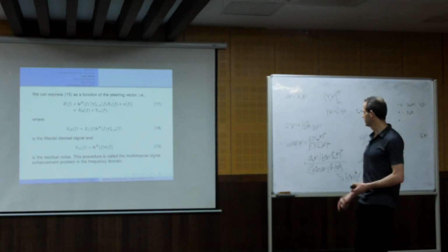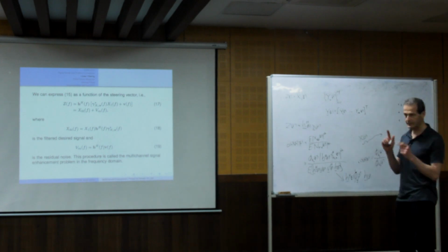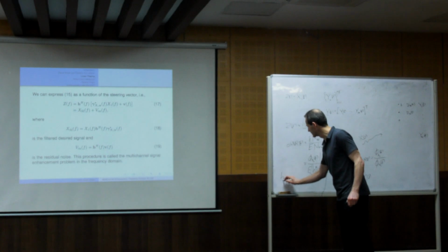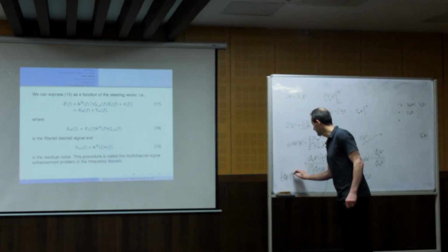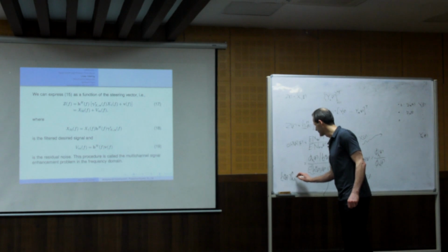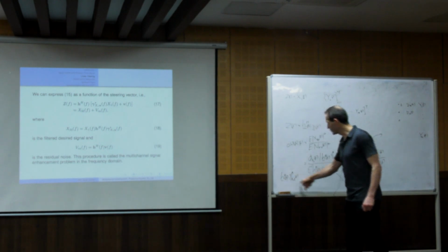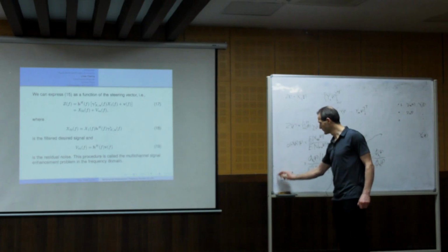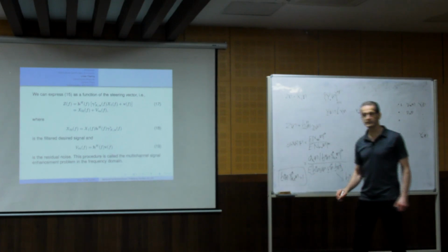Exactly. Okay. So for MVDR, we will require that H multiplied with gamma, the coherence function between X1 and X, will be 1 for all frequencies.